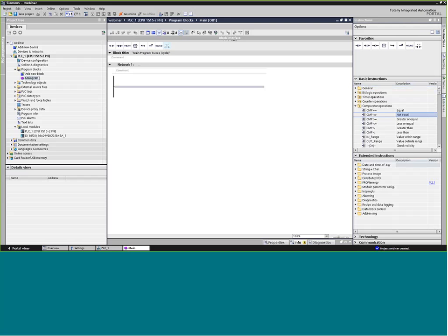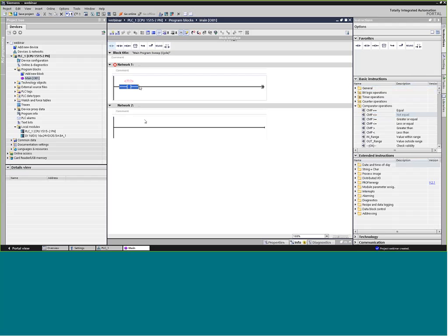So in any case, let's write a little simple code just to get an idea about the environment here. We're going to do a little sealing circuit, and sealing circuits are typically how ladder logic was designed to simulate what a relay logic schematic looked like. So we actually have a power bar, and we're going to pass power through if different contacts have closed. If I grab a normally open contact and bring it down into the first network there, that would be, for example, a start button.